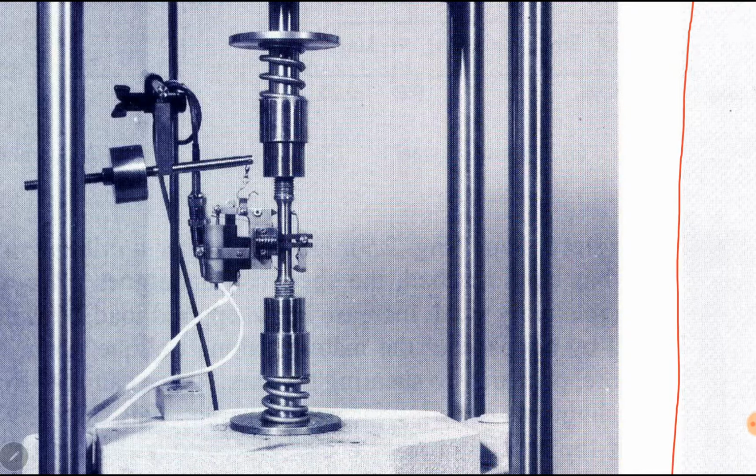What is necking? Necking is simply a gradual decrease in the cross-sectional area of a ductile material before fracture. You can see here in the diagram a neck in the middle of the specimen. As soon as the cross-sectional area of the specimen decreases, after some time the material suddenly fractures into two pieces. The structure can be seen here. It is a cup and cone shape. This is the cone and this is the cup.